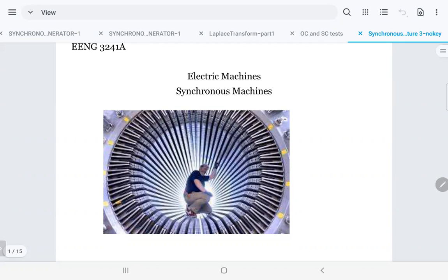Then what happens? You have copper loss, and then you get the output power. So it's important to know that the output power is equal to the developed power minus the copper loss. What is the developed power? It's the mechanical power converted to electrical power inside the generator, but minus the rotational losses, of course. That's the important fact. So that's how you can get it.